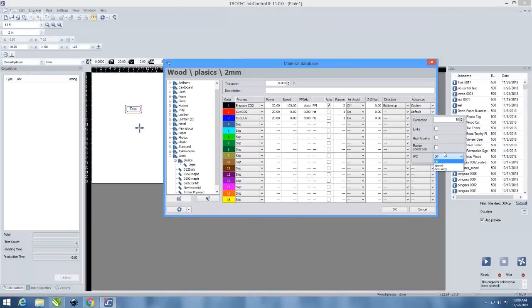Sticky edges are usually more due to the frequency being used for the cutting. So you want that on engraving plastic to be as low as possible. So 1000 is really where you want to be for that. If you're trying to cut it at higher frequencies, you're definitely going to get a stickier edge for sure. But position on the plate doesn't really play a factor in that. Perfect.